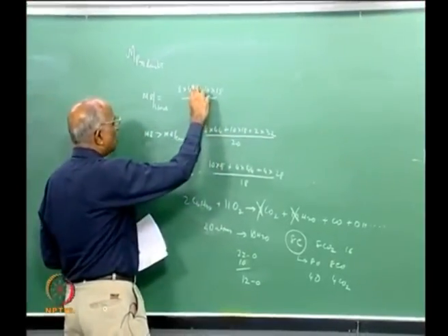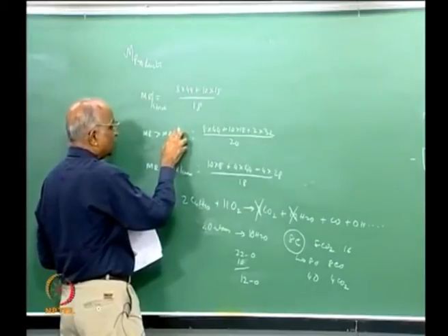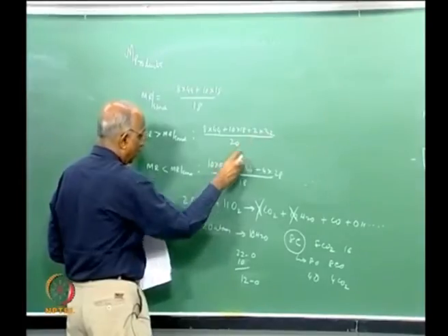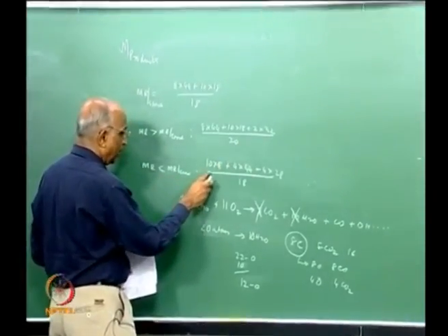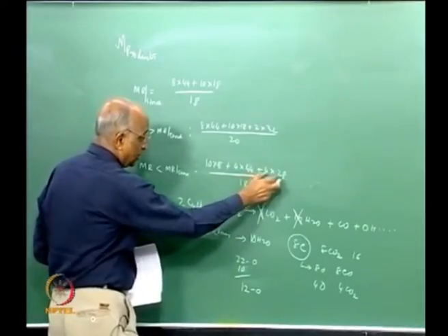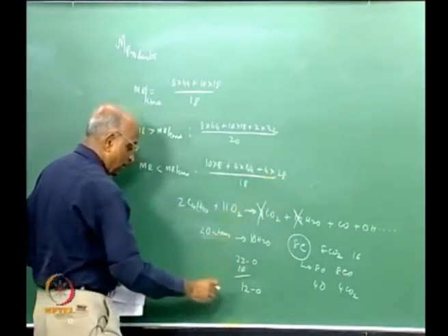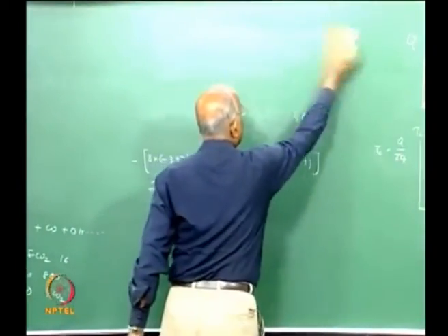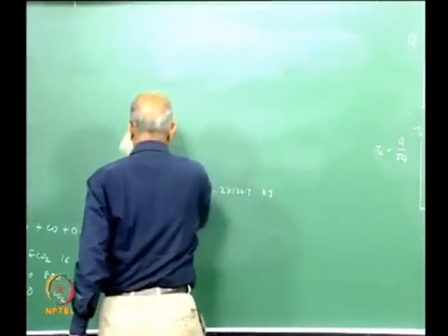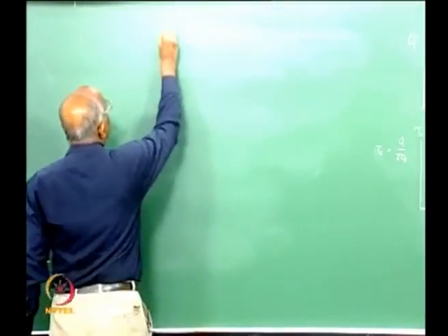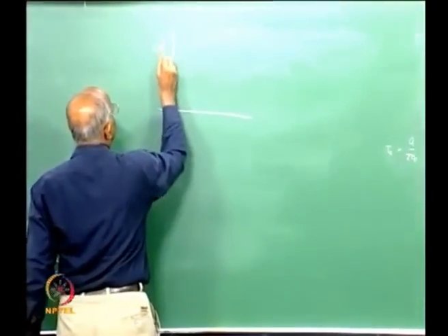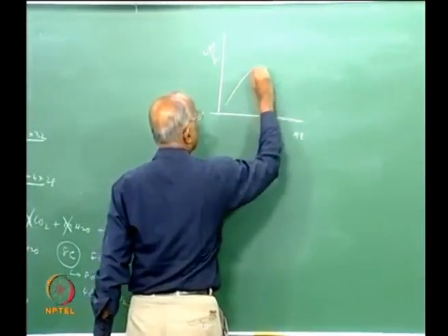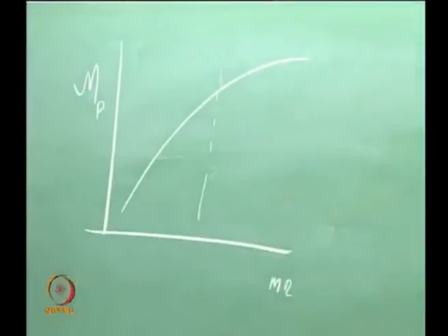What we find is, for stoichiometric I have this. When the mixture ratio is greater than stoichiometric, I am adding higher molecular mass substances, therefore the molecular mass is higher. If I have mixture ratio less than stoichiometric, I am adding substances which have lower molecular mass. Rather, I can plot this: as the mixture ratio increases, the molecular mass of the products increases, with this being stoichiometry.